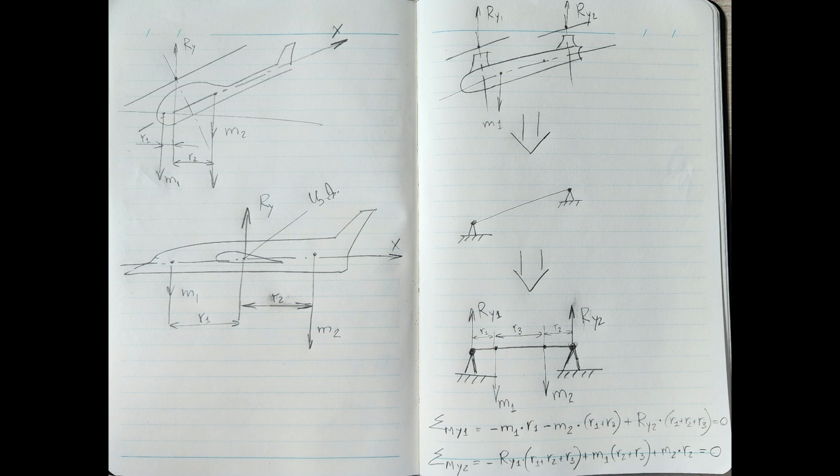Generally speaking, this example demonstrates a number of reasons why quadcopters have become the most common UAVs. In particular, the first reason is the simplicity of calculating the load on the propeller. The scheme shown in this sketch is, generally speaking, nothing more than a centering calculation scheme for helicopters of the longitudinal scheme, such as the Chinook CH-47, Sikorsky CH-54, Boeing Vertol CH-46, and Yak-24.